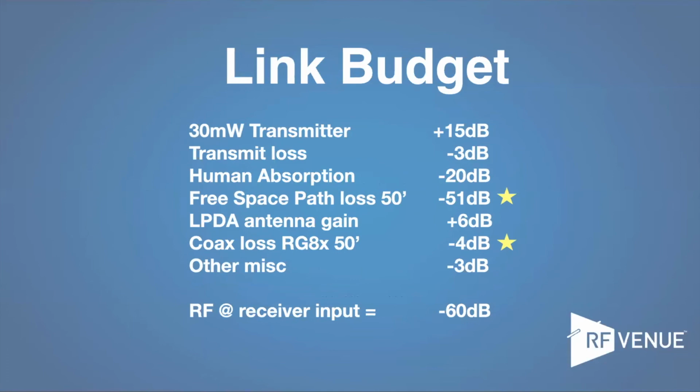So that minus 51 number would look a lot different if you were at 25 feet, or you had a near field antenna, or you had a lower power output setting on your transmitter but a more localized reception area. I'm just making more of a comment. I don't know if you have anything to add, but if you had to focus on two areas to experiment with to get the link budget right in the sweet spot, see if you can do it with the lowest power possible on your transmitter, which has other side effects like extending battery life.